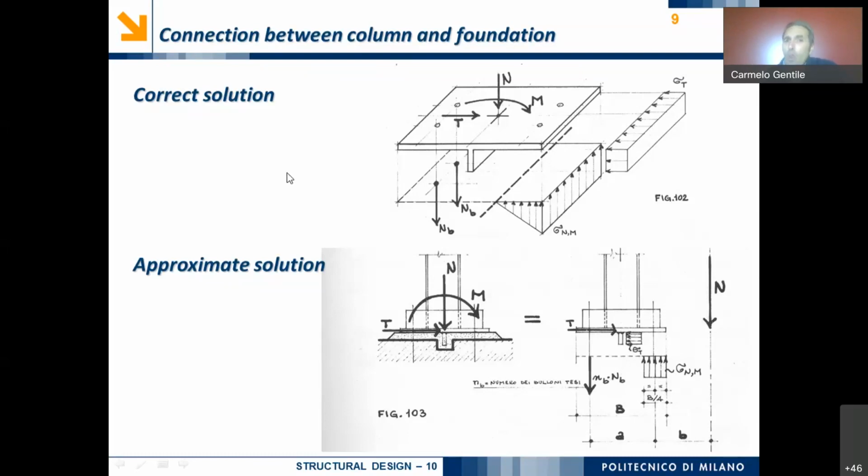And so we will have basically a third unknown to be evaluated. Since we need to find a third unknown, we also need a third equation, a third condition. And the third condition is directly supported by the fact that our plate is assumed to rotate according to a rigid body motion.